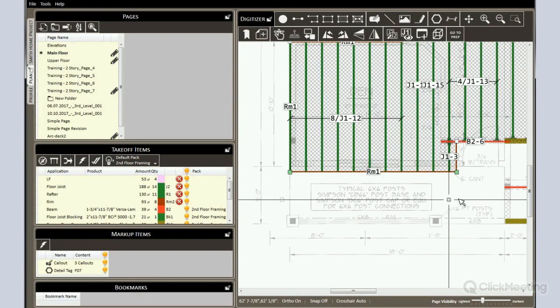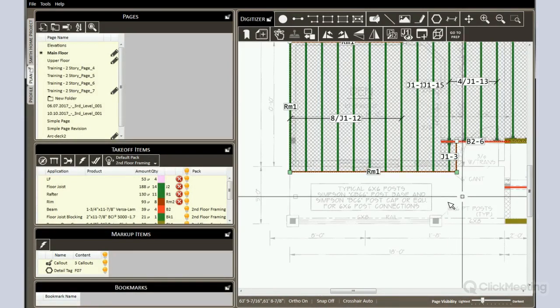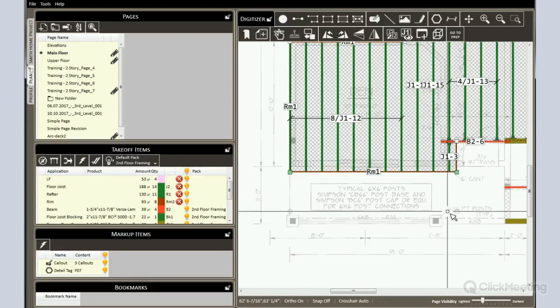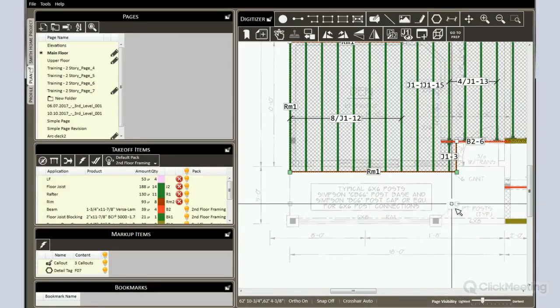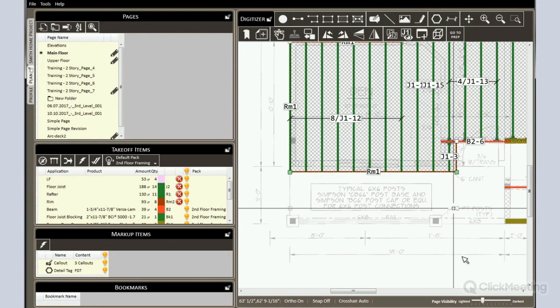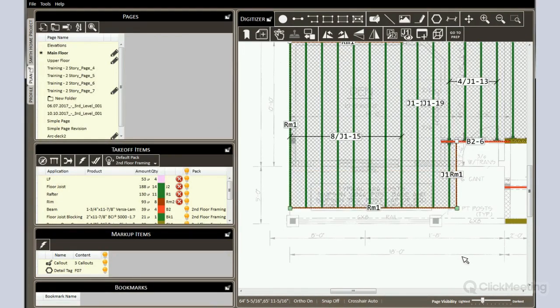Again, without holding shift, the nodes kind of float anywhere, but if I push shift down on my keyboard now you can see that they are starting to follow that snapping or that ortho movement. And I can drop it and let go, and they move down in that direction. So again, ortho node movements activated by using the shift key on your keyboard.